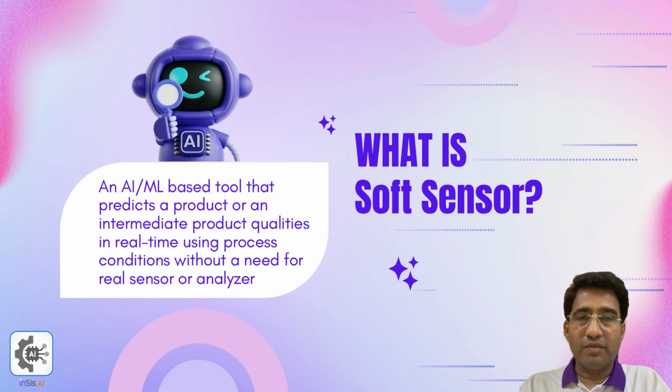So what is a soft sensor? It is an AI/ML based model that predicts the product and intermediate product qualities using process information like reactor temperature, reactor pressure, maybe column reflux ratio, kind of operating conditions. It takes real-time data from the process using DCS or PLC or SCADA kind of systems, feeds it to the AI/ML model, and then predicts the product qualities. The product qualities are then written back to the DCS so that operators can see the real-time product qualities.